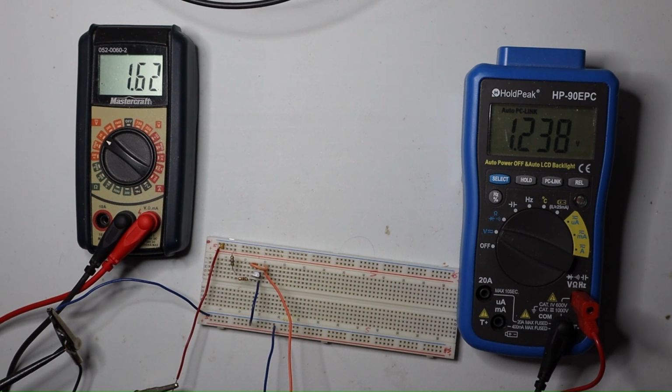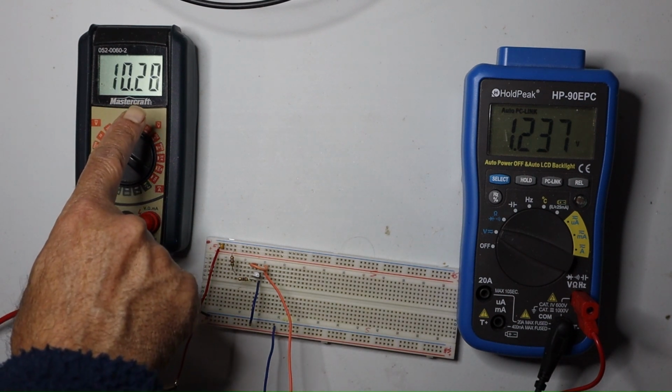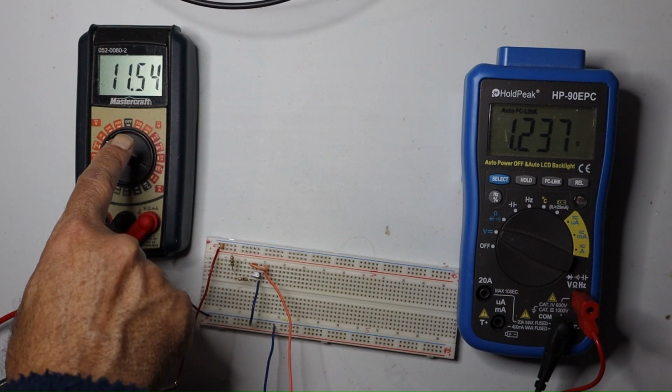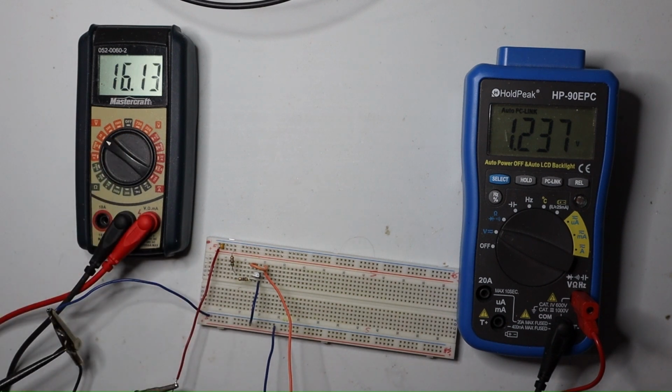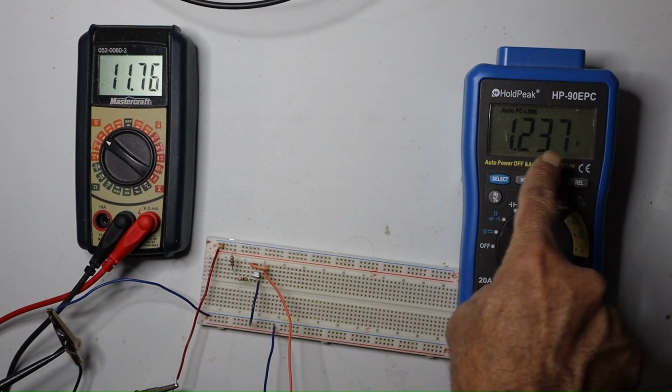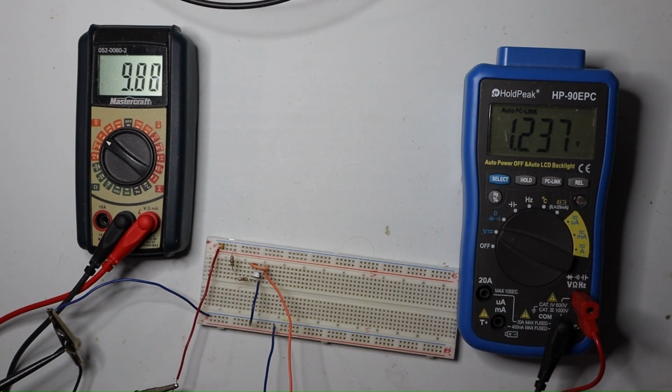As you can see, I am increasing the input voltage and the output voltage remains almost constant at 1.24 volt. Now you can see almost 7 volt input and the output remains the same. The input voltage is still going up, with no change so far at the output voltage. Now it is 10.2823 and it is still going up, and the output voltage remains around 1.24 and is not varying much.